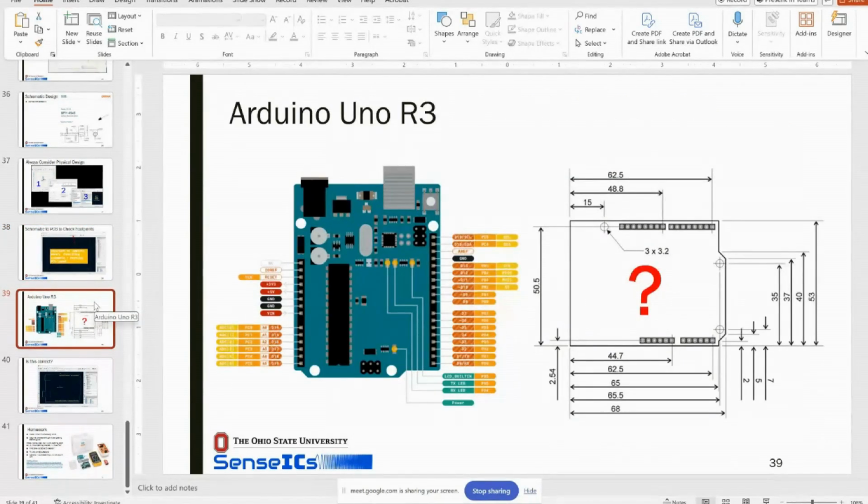The most important thing I want to talk about is that I do not trust these libraries that come to me from an outside person. Even if it comes from TI, even if it comes from Analog Devices, I don't trust what came out of that library. So your job between now and the next time is to tell me, is that Arduino R3 footprint correct to plug in to the Arduino itself? Will it work? So how do you figure that out?